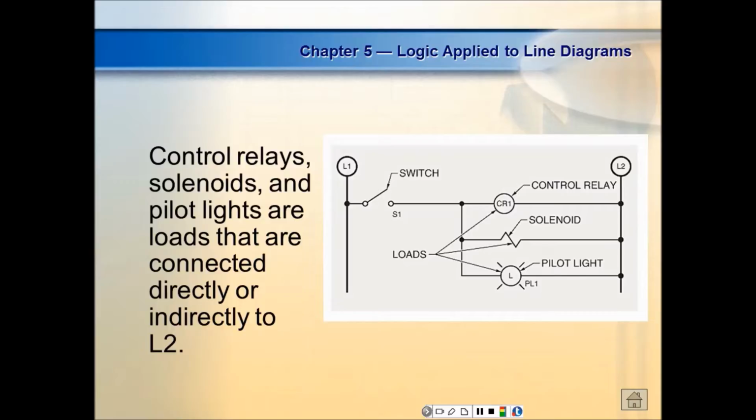So normally we can connect things in series, but it's not going to be a series circuit. When we start talking about series circuits, we're talking about how the loads are connected. Here in the control, we have no series circuits. We can hook control devices in series, but it's still not a series circuit. You'll understand the difference. So when we start talking about a series and parallel circuit, we're talking about how we connect the loads. So this would be a parallel circuit, even though that switch is in series, it's not a series parallel circuit, right? You understand?